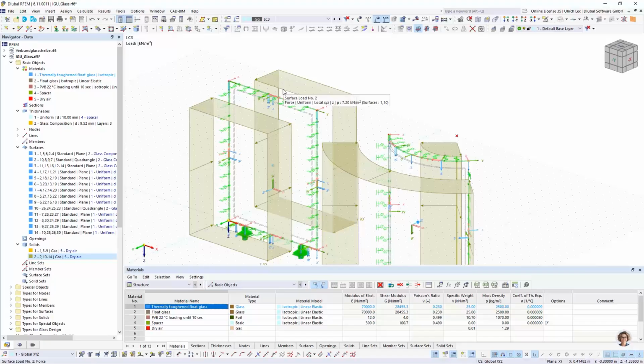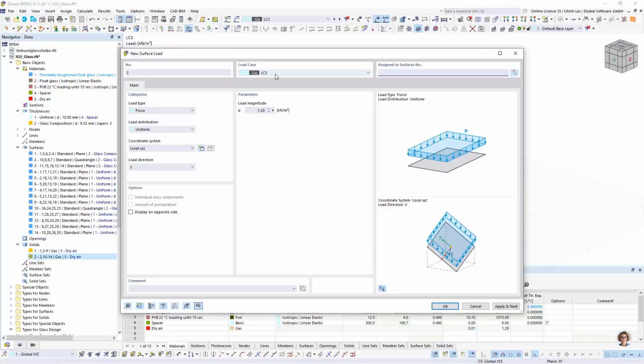So then I can continue with the pressure difference with the atmosphere. It's given by a value of 2 kilonewton per square meters, and it's acting in the same direction like the altitude difference. So I get here load case 4.